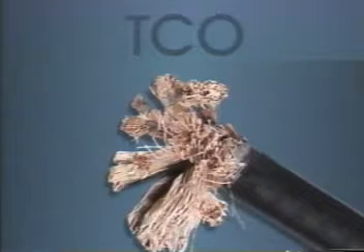But you might find it with a protective jelly put inside of it to keep water and moisture out. Getting water inside a telephone cable gives us a lot of noise and a lot of problems. So by putting a moisture protectant device like a petroleum jelly or some other kind of device that fills up all the cracks in the cable, keeps the water from coming in. That would be much more appropriate if the cable laying in the ground than hanging on a pole. So we have different ways we can build our cable. Some of the cable actually has a pulp or a paper-derived product wrapped around each individual copper wire. We tend to find this more in the bigger cable coming out of the central office that's not going to be re-entered and re-spliced a lot.